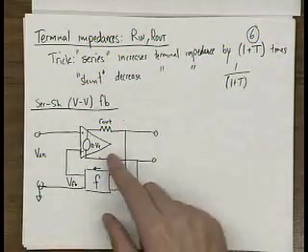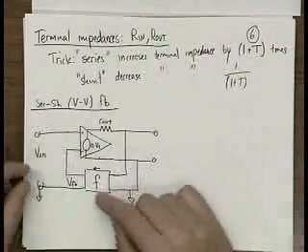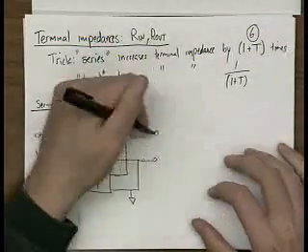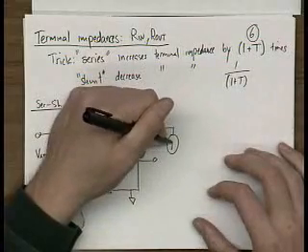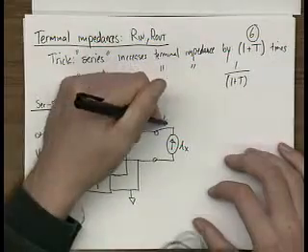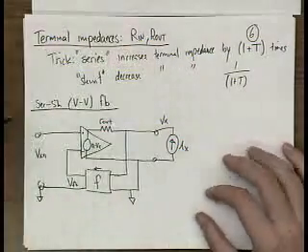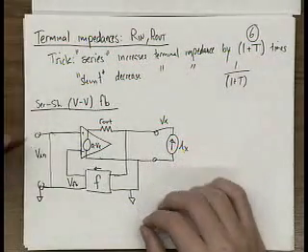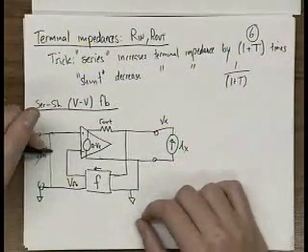It doesn't load the circuit. So if we were just to look at the output resistance of this amplifier block, we'd get R out. Okay. Now what we do is we inject a test current here, IX, and look at VX. Okay. And we assume that V in is tied to 0. So we're grounding out V in.